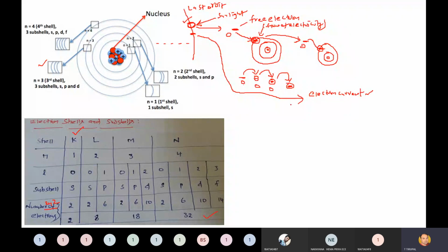Now similarly, you go from right to left. What is moving from right to left? A hole is moving. See, this is a hole, this is a hole, this is a hole. So even if you combine all these holes, there is another current which is called hole current. Hole current is created. So now we can obtain the total current here. What is the total current obtained here? Total current is equal to electron current plus hole current. So this is most important.